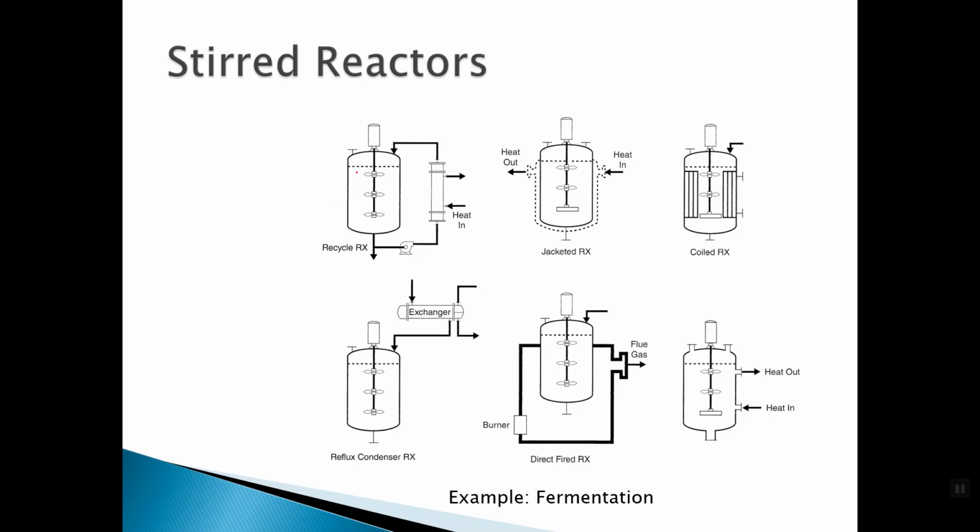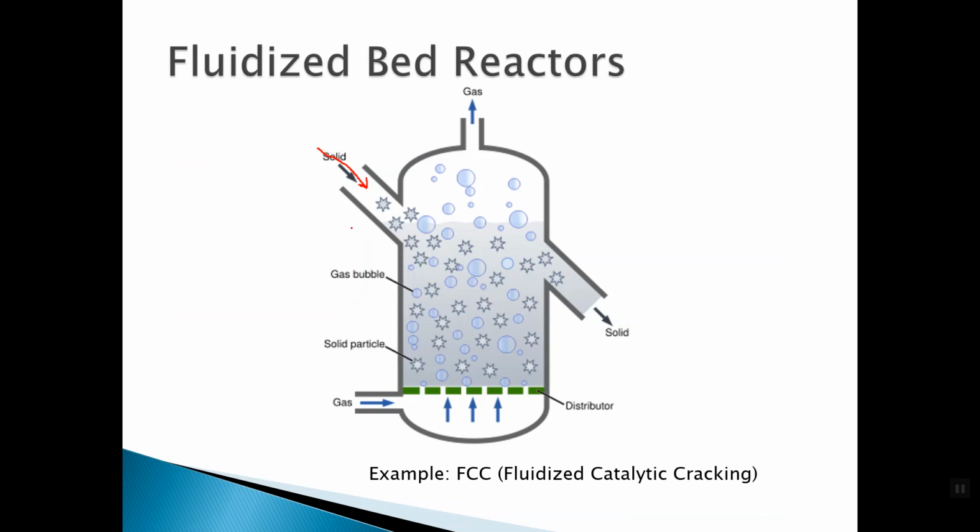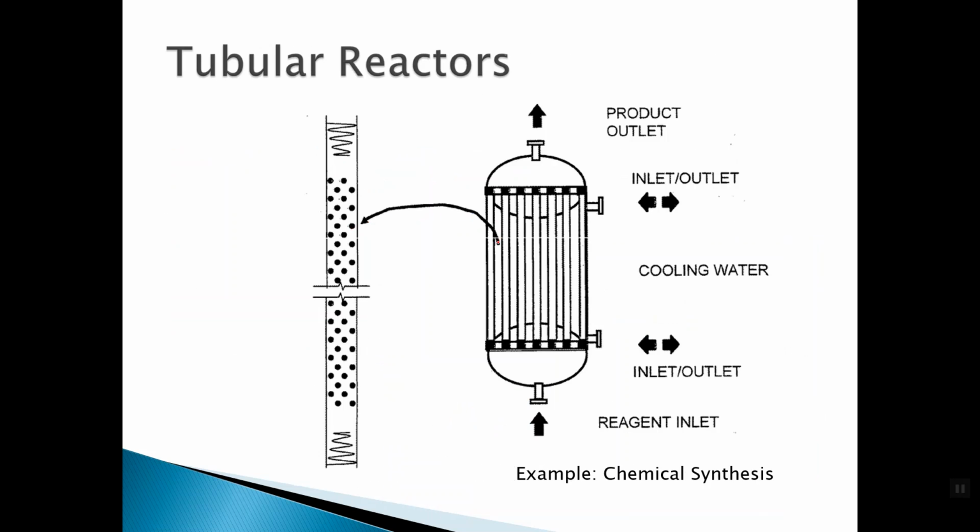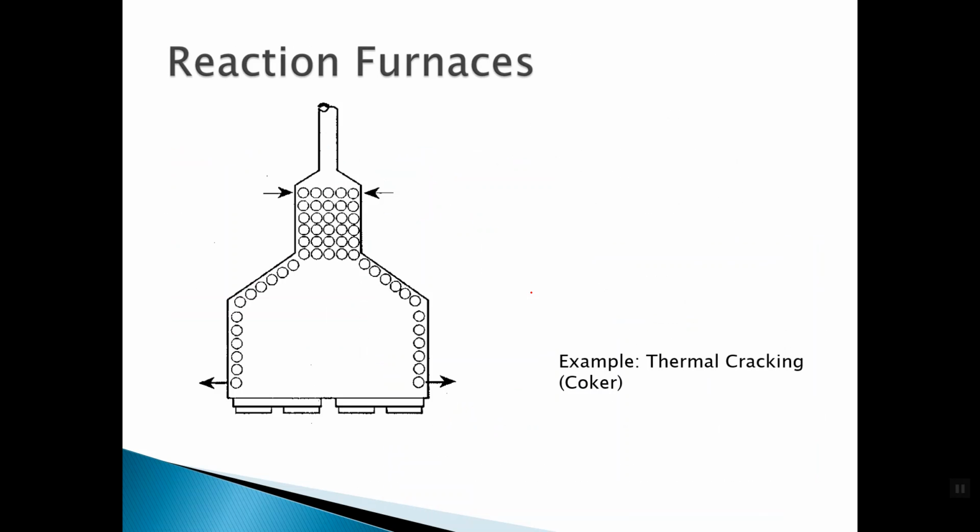And so the temperature is not going to be even all throughout. It's going to have some hot spots and some cold spots. We want to minimize that, but it's inevitable. Sometimes the top of the tank might be a little bit hotter than the bottom of the tank. Well, if the temperature needs to be very precise and controlled, we put in the shell and tube heat exchanger and have the reaction happen right in there. That way we can really maintain the temperature correctly.